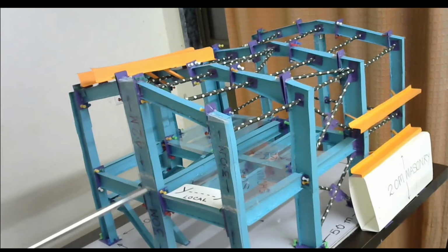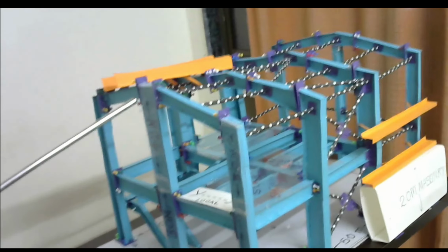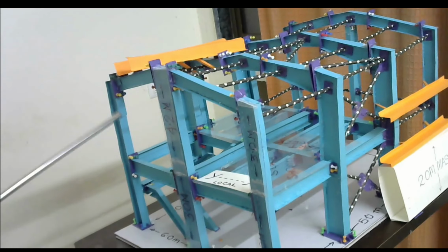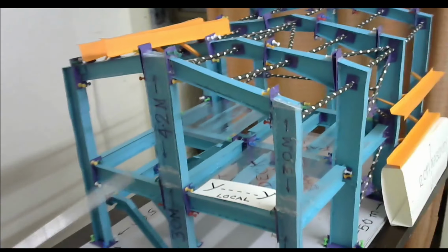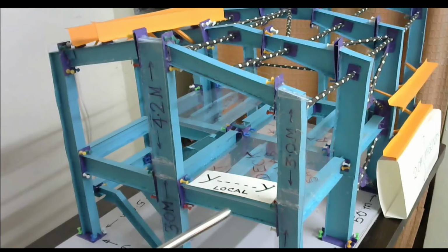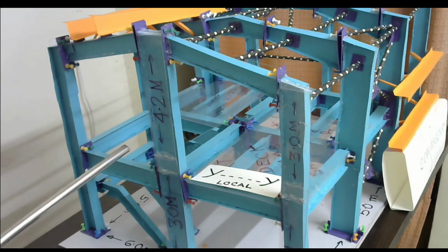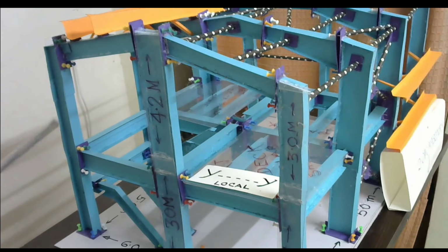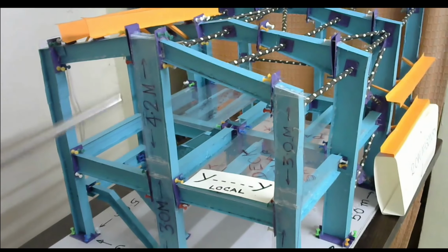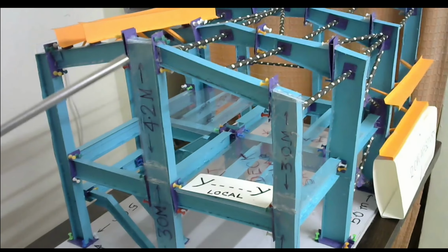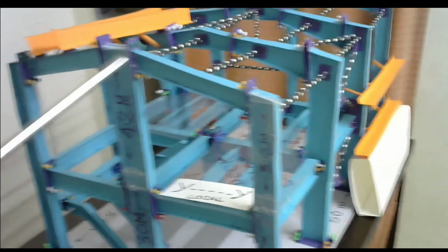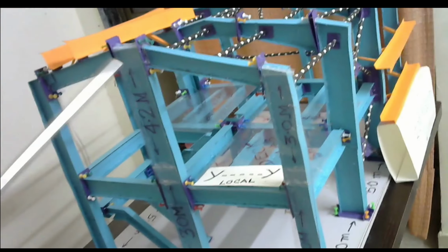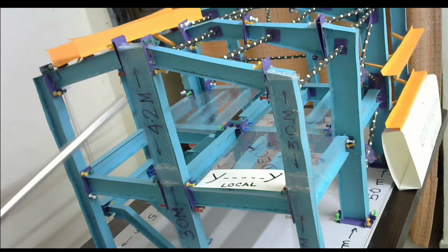Now again coming to the LZ parameter, fixed at bottom, fixed at top. So again it is a sway frame, with no X bracing or cross bracing here, or any kind of eccentric bracing. It itself is a portal. So when a portal moment frame resists a lateral load, it has to be considered as a sway frame.